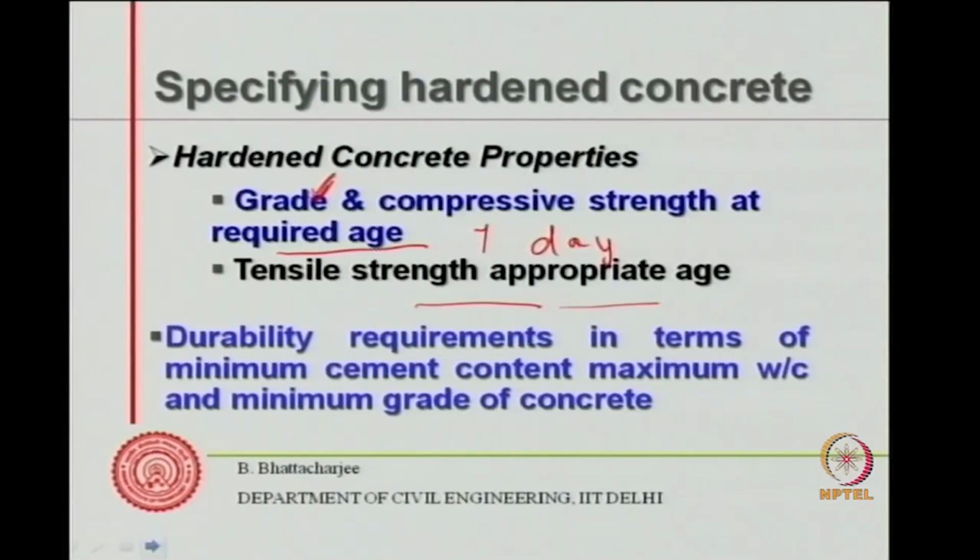So, although at the moment most of the codes don't quantify the durability in terms of, let us say, service life, we understand durability is a property related to its endurance to various kinds of exposure conditions. And our understanding in a quantitative way of this durability property is limited. At the moment, from the knowledge of the mix proportion and knowing the exposure condition, we may not be able to say how long concrete would be able to perform as required.